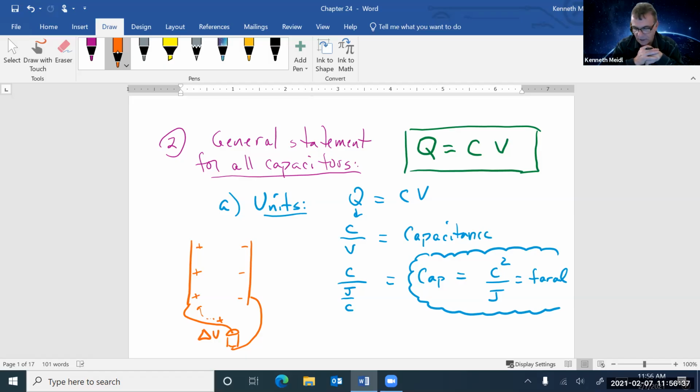And capacitors can hold charge for weeks, months. So when a technician goes into something like an amplifier, one of the first things they will do is get a couple of wires, maybe with a light bulb connected to it, and go across the capacitors. When the light bulb lights up, they know there was charge there, and the positives can see the negatives. So you're just getting a wire and connecting the two plates together, and then they neutralize, right? And now you're making it safe.